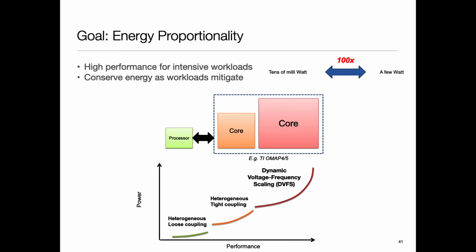And then platforms often have heterogeneous cores, which may have a different ISA and are really optimized for something else. A great example here would be on iPhones, they have the so-called motion processor, which handles the data coming from some of the sensors, the inertial sensors in particular, and this is where they run some models to extract your activity state.